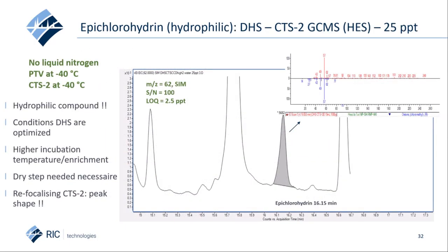A currently hot application that can clarify more the previous slide is the analysis of epichlorohydrin in water, for years analyzed by purge and trap as the standard technique to be used, but suffering with low robustness in routine and no flexibility towards general screening of a wide range of volatiles, especially also the hydrophilic compounds and other volatiles with very diverse chemical properties. In fact, when applying DHS with refocusing here, DHS parameters needed to be optimized,